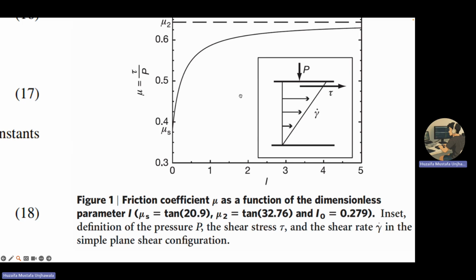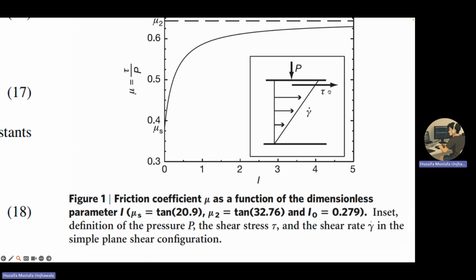There are some more parameters: the curve this takes from mu s to mu2 is defined by a few more parameters based on the particle's grain size, the particle grain density, and the bulk density of the material. And these options are also available to set.